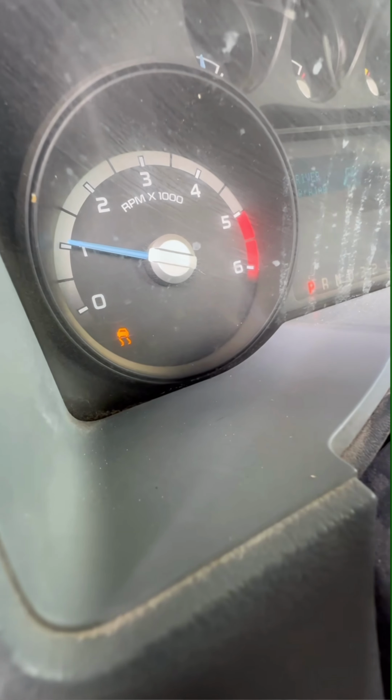And if you notice, the mass airflow sensor was missing a screw and it was new. They had just replaced it. But the problem is that they used an aftermarket sensor. Got an OE sensor installed already. Let's go retest. All right, there we can see intake air temperature is reading closer to the ambient air temperature, and she starts right up and runs good now.